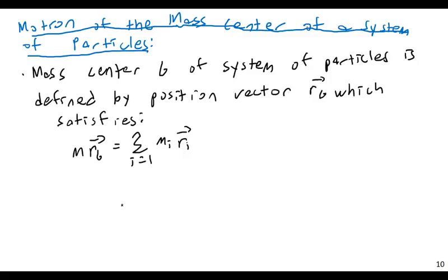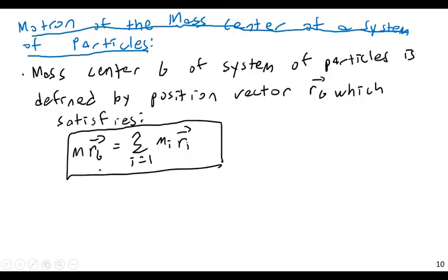So then let's take that and do the derivative here. This is mathematically defining what the mass center is. It is basically saying that the mass center is a position, a location. There may not actually be anything at that position, but the position. So really, all that the mass center means is a point in space, and if I multiply the mass times that position vector, that would be equivalent to the summation of mi ri. In other words, what we're talking about is almost the centroid of the system. Remember centroids from earlier in statics class? We're looking at the mass centroid of the system.